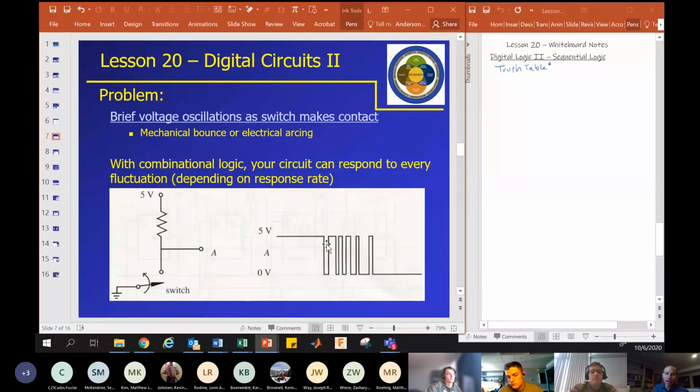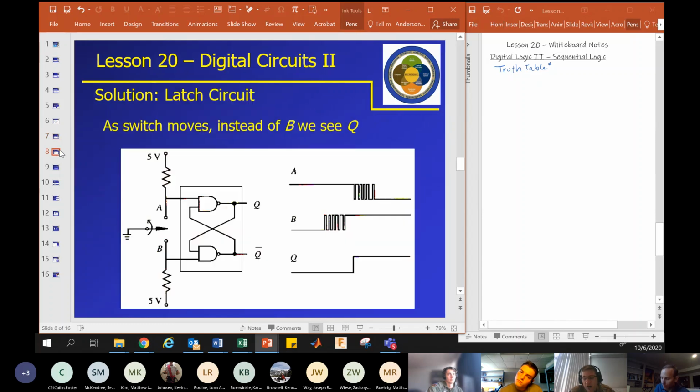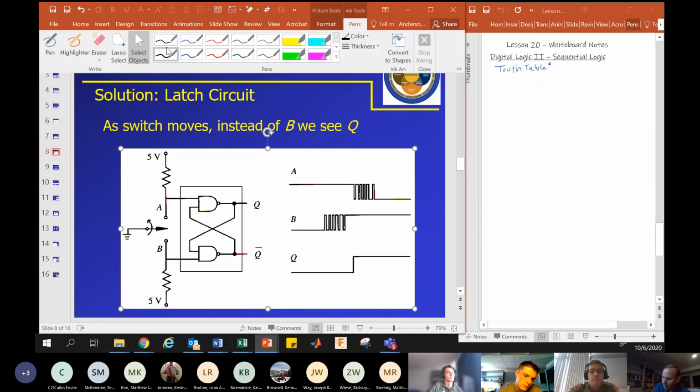And if you needed to do that, this bouncing would really mess you up, because in this case, it should only record one switch, but instead it's getting 1, 2, 3, 4, 5, 6, 7, 8, 9 or 10 switch flips, which is not what we want. Okay, so this is a circuit that's designed to overcome that problem, and it's called a debouncer circuit.